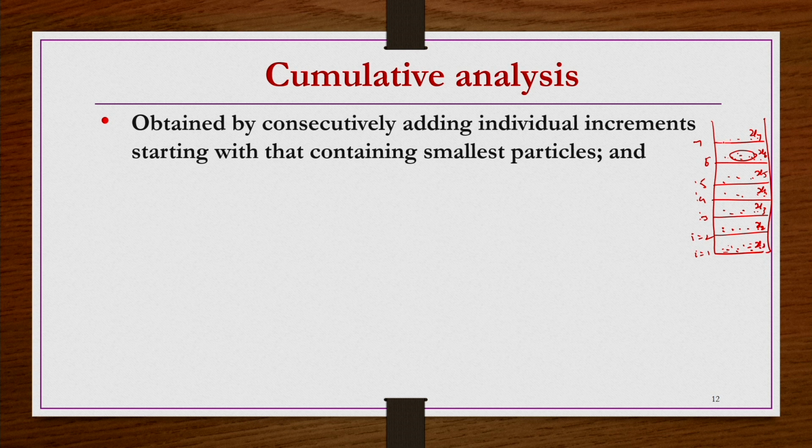The screen opening here is dp7 for the 7th one, likewise dp6, dp5, dp4, dp3, dp2 and this is actually the pan, so it should be 0 opening. So, now cumulative analysis, what we do for the dp7 row, the cumulative fraction x7, what is the fraction of material that has a size smaller than dp7, right.